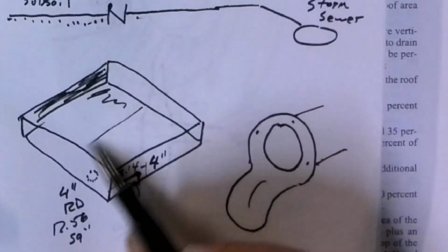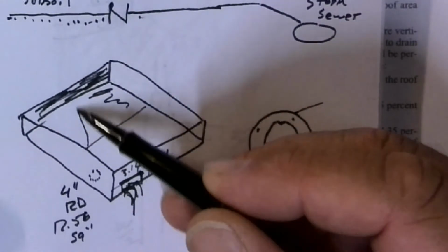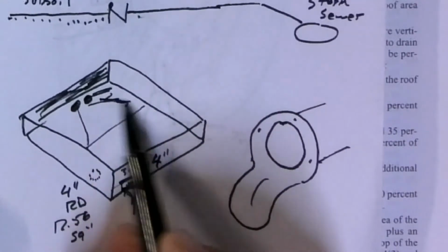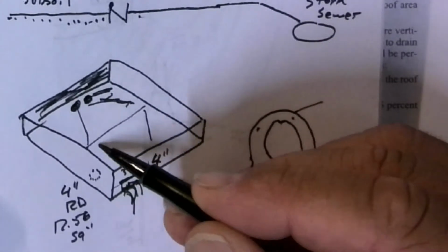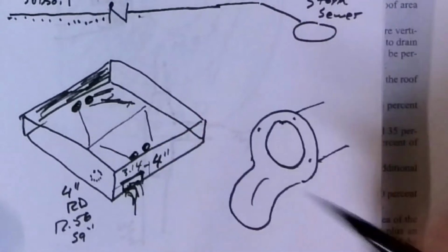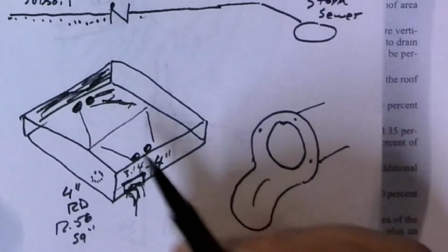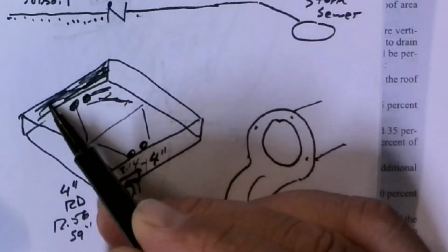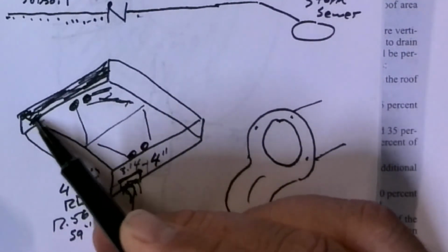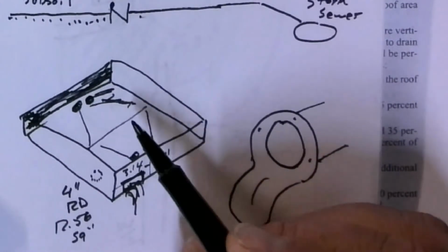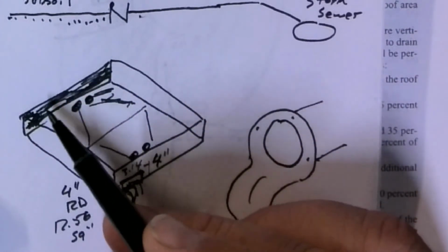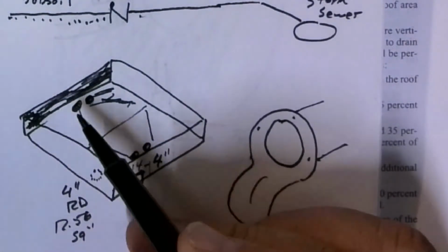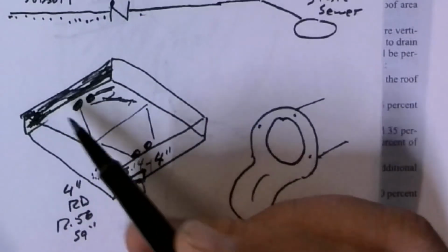Let's say that this roof is split and everything drains down this way to our roof drains that are right here. And then this one drains out this way to the 2 roof drains that are over here. Okay? One's primary, one's secondary. Let's say that this parapet wall here is the only thing that's up. So that's all you see is this guy. Well, rainwater is going to collect on this, right? And then it's going to come down onto the roof. And so we have to accommodate for whatever rainwater comes and hits this.